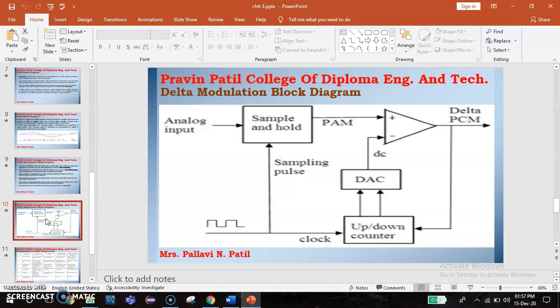In this block diagram, DM stands for the delta modulation technique. The details are described below. If the sampling interval TS is reduced, the correlation increases. If we sample a band limited signal at a rate much faster than the Nyquist rate, the adjacent samples should have higher correlation. This sample to sample amplitude difference will usually be very small.